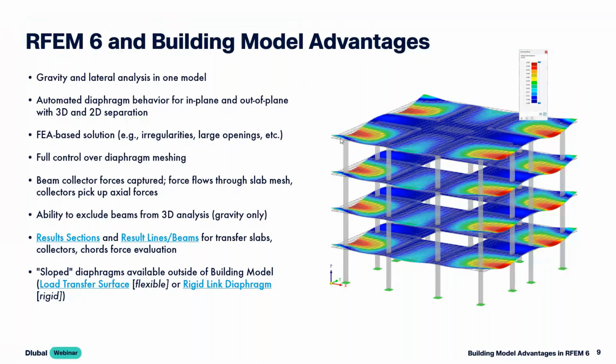And we have the ability to automate this diaphragm behavior for both the in plane and out of plane stiffnesses. And in the case of the semi-rigid or rigid diaphragms, we will go ahead and separate out the analyses into that 3D and 2D for our floor design versus all of the other elements taking those additional lateral loads. Now, as I mentioned, RFEM is still an FEA-based solution, right? That ultimately, this is a very powerful program applying FEA principles.